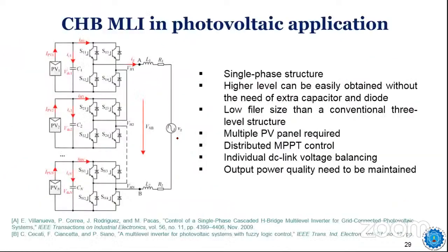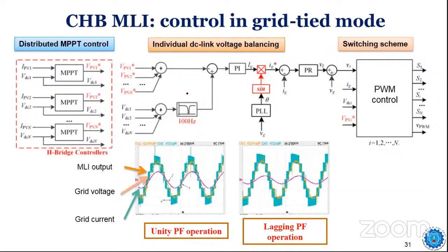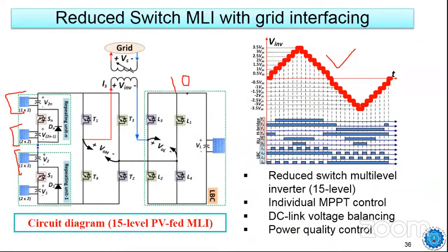So I am considering a symmetrical type. For this type of system, if you develop a 15 level inverter, you connect 7 H-bridges, and then you can develop a 15 level output. 7 H-bridges means the number of switches will be 28. So instead of connecting 28 switches, see how compact I have made it. I have connected only 10 switches to produce the required 15 level output.